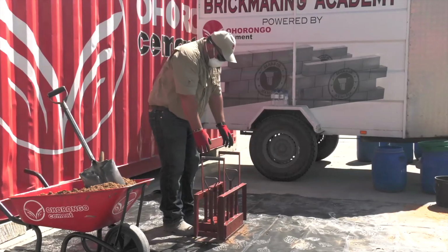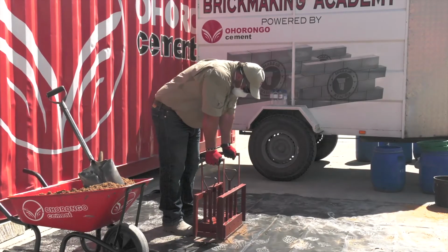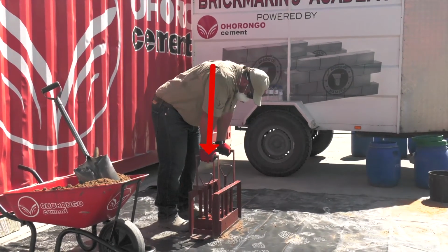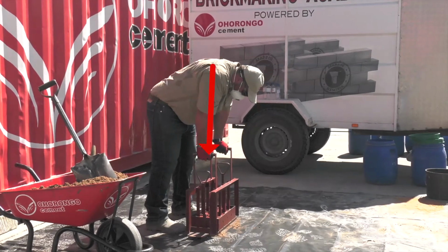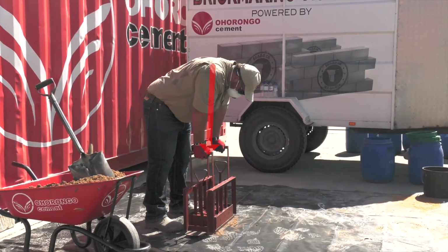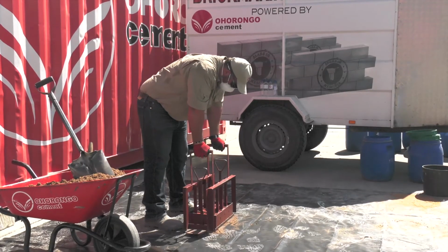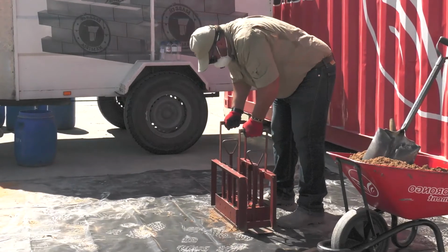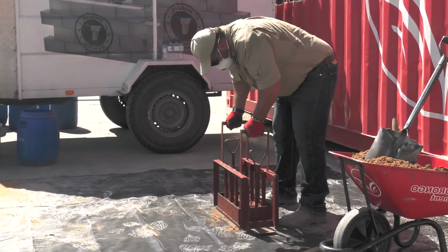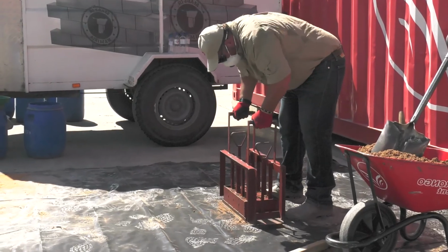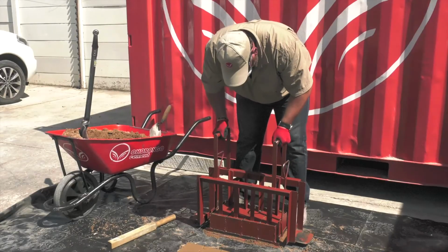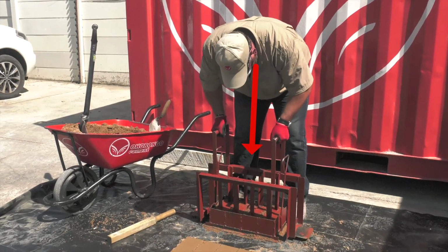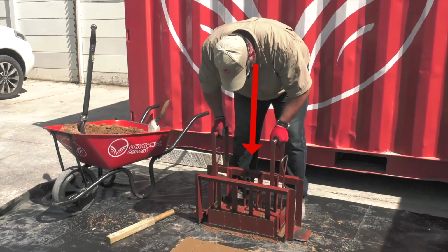First, utilize body weight by putting pressure onto the mold and push down hard. Make sure that you are directly above the mold so as to ensure an even surfaced brick. Neglecting to do this will result in a skew brick. Now, use short bursts of compaction movements with the top part of the mold to properly compact the bricks. Again, ensure you do this directly above the mold. Do this for about 5 seconds.